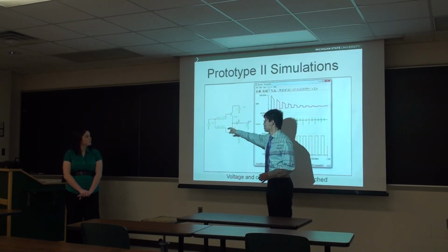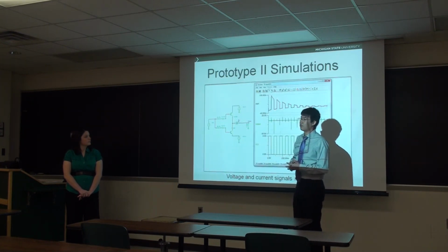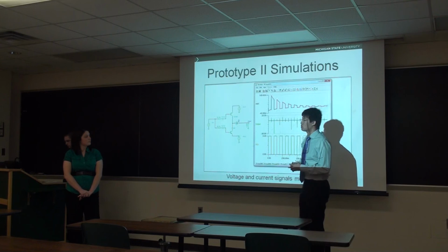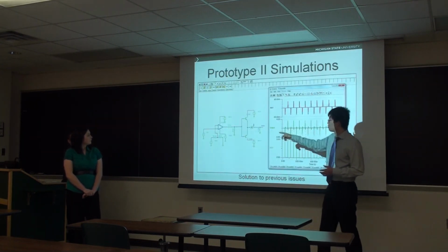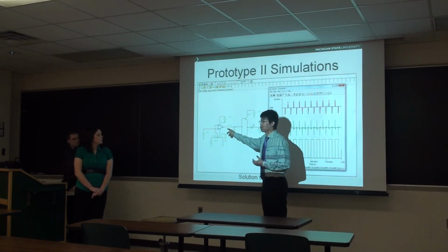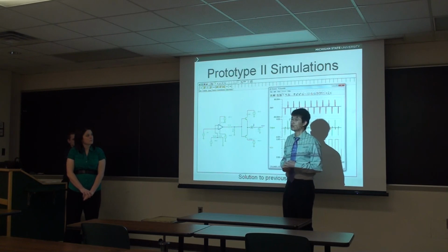The signal cannot get below the negative pulse. So when I designed a new circuit, I used op-amps as a comparator. I basically transfer from 0 to 5 volts to -5 to 5 volts.